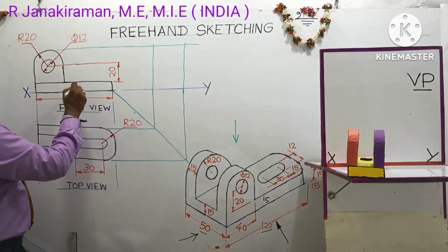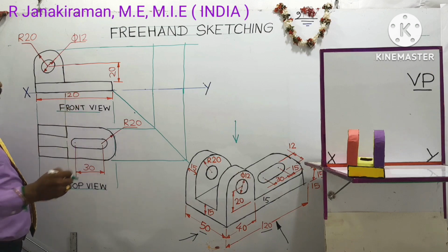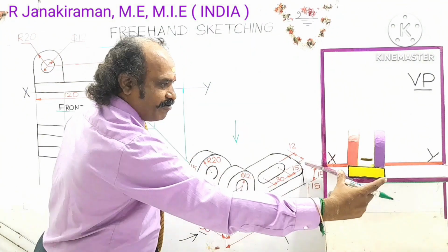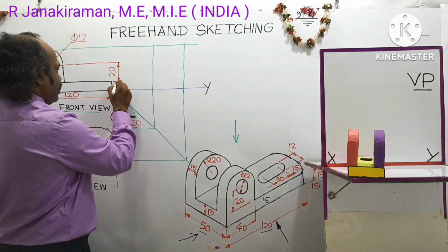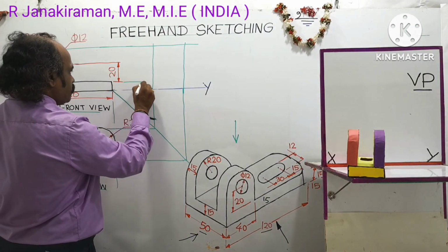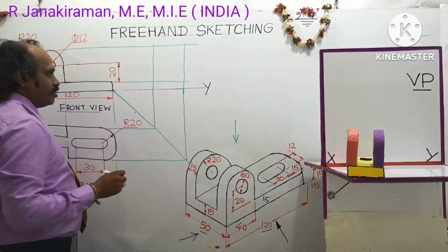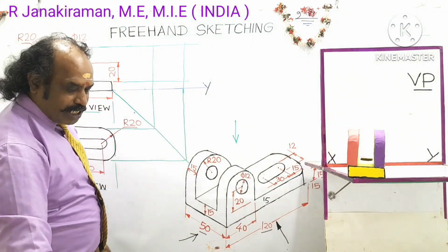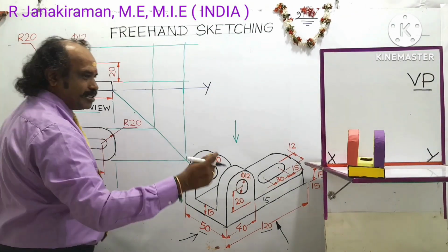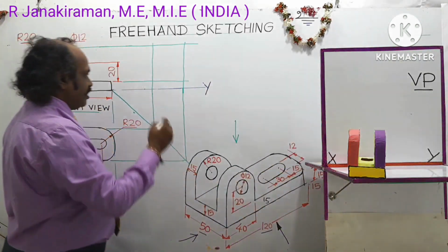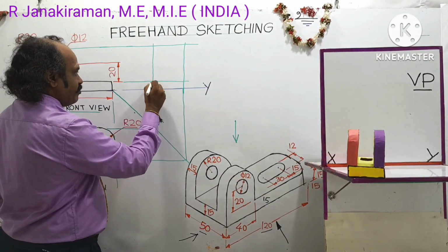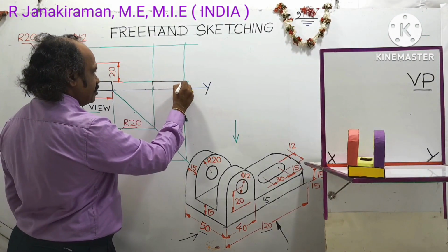Okay. And the base thickness is given as 15 mm. So same as breadth, we will also have the base thickness as 15 mm given in the diagram. You extend this base height. Okay. So with this as reference, using an HB pencil, construct a base. The base seems as a smaller rectangle, this yellow color part on the lower surface. So let us draw it by HB pencil. It's a base edge.